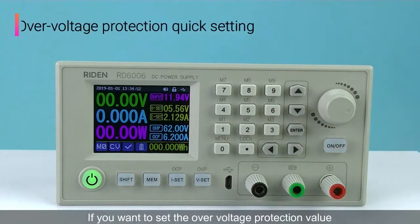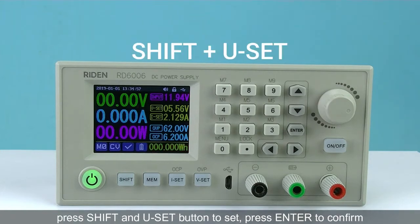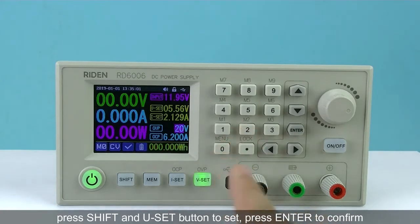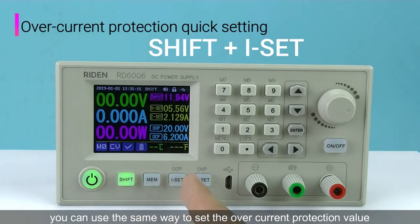If you want to set the over voltage protection value, press the Shift and V set button to set. Press Enter to confirm. You can use the same way to set the over current protection value.